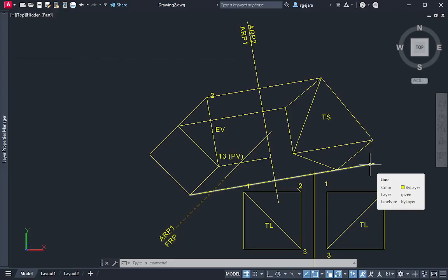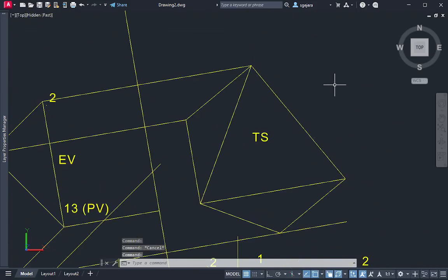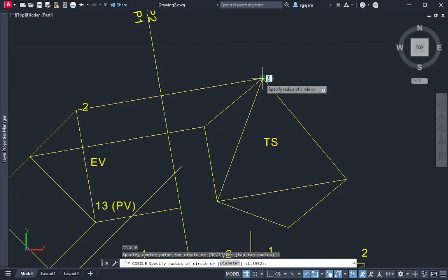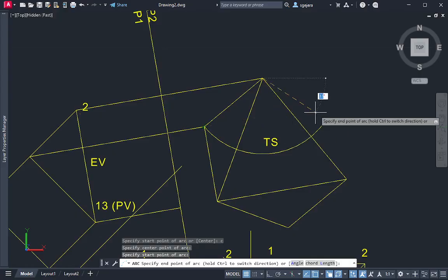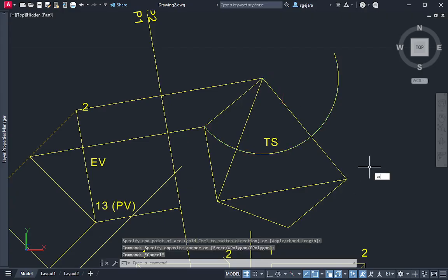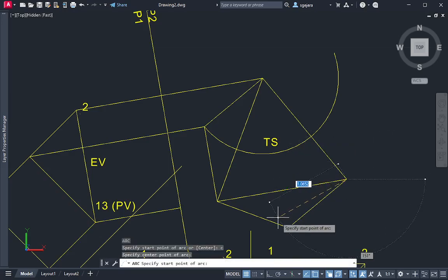So, alam ko kasi regular shape to. So, whatever this side here is, same lang siya sa side dito. And I also know na same din siya sa side dito. Tama? So, what I can do is, again, I can do the same technique, no? Parang create a circle. Pwede ding arc, no, if you want. Pwedeng arc. If you want to be cleaner, pwedeng arc na ganyan. And using this same arc, create tayo ng another arc. A for arc, C for center, ito.